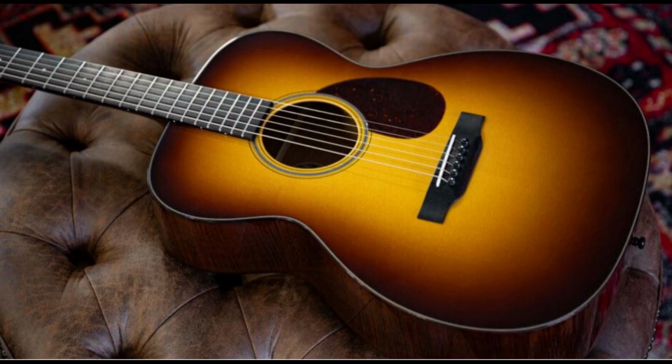The types and models of pickups used can greatly affect the tone of the guitar. Typically, humbuckers, which are 2 magnet coil assemblies attached to each other, are traditionally associated with a heavier sound. Single coil pickups, 1 magnet wrapped in copper wire, are used by guitarists seeking a brighter, twangier sound with greater dynamic range. Modern pickups are tailored to the sound desired. A commonly applied approximation used in the selection of a pickup is that less wire, lower electrical impedance, gives a brighter sound, more wire gives a fat tone.